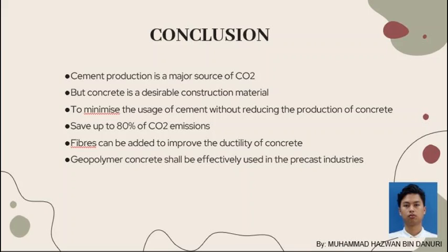Geopolymer concrete is well known for its promising mechanical properties, acid resistance and fire resistance, and therefore is a potential alternative construction material with comparable properties to OPC concrete. The constituent of geopolymer concrete shall be capable of being mixed with a relatively low alkali activating solution and must be curable in a reasonable time under ambient conditions. Geopolymers emit approximately 80% less carbon dioxide than OPC during production, making it a more environmentally friendly building material.